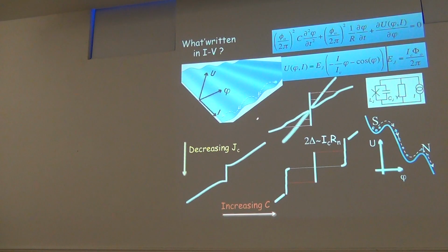And so here, the slope of the washboard potential depends on the current, as we can see here. This is for zero bias, so we have just a simple sinusoidal function. When we increase the current, we get this bending, and then obviously we change the condition for which the ball could roll down the washboard potential.